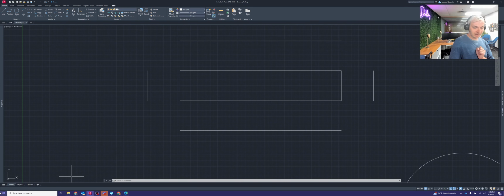Let's take a look at the bottom right corner of the screen here in AutoCAD. So there are these different settings that you have down here. So grid mode, or the F7 key. All that does is it makes a sort of grid for the user to be able to see along the lines of what they're drawing. If you like having that on, you're more than welcome to keep it on. I am not going to keep it on myself. I usually don't.